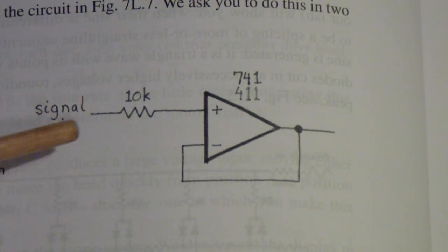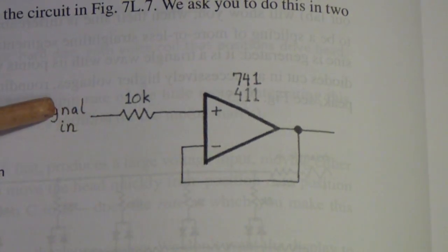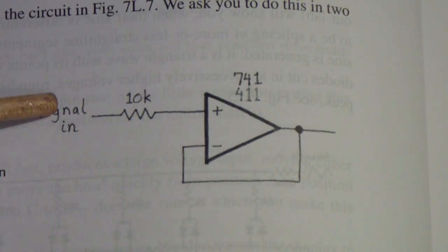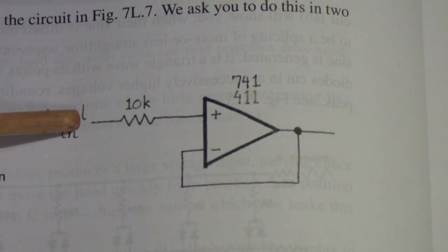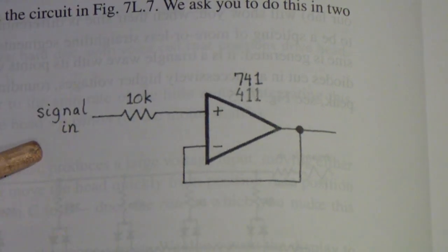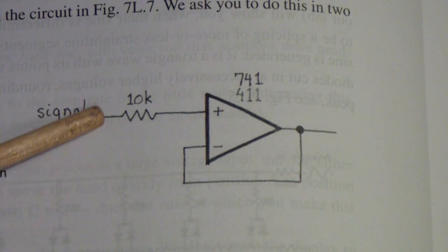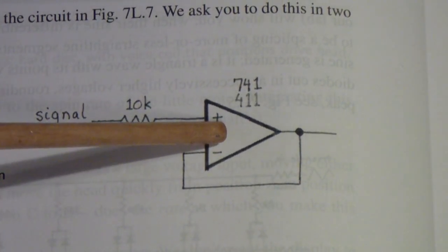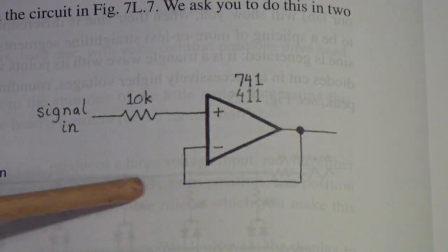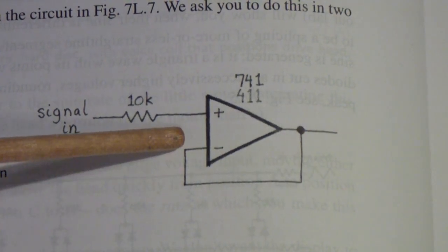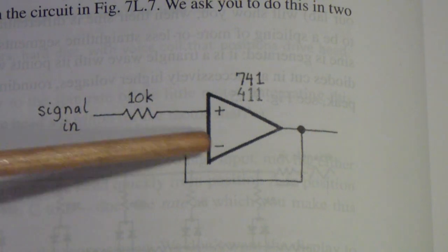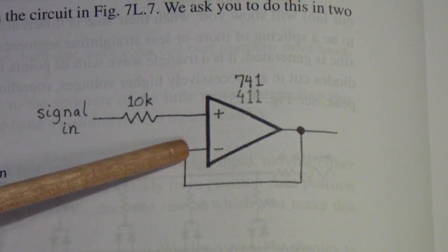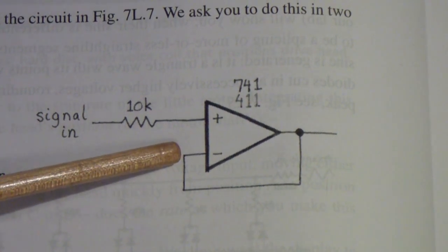There is a signal, in this case coming from the waveform generator of the Analog Discovery, and I also have channel 1 of the Analog Discovery connected to that same point, so we can monitor that. A 10K resistor, and then a 741 op-amp that is connected in a simple follower configuration. In other words, it's a unity gain circuit. The output is fed back to the inverting input without any